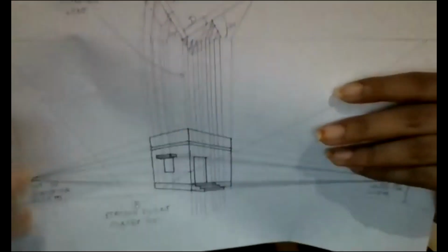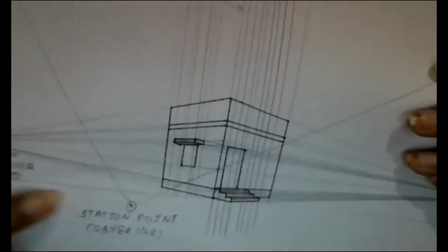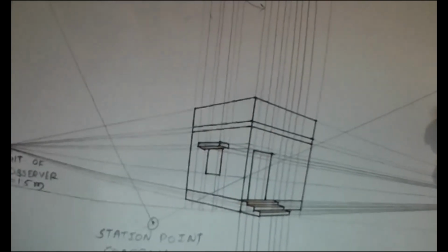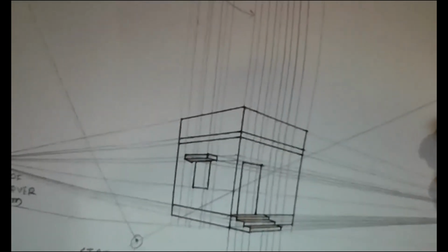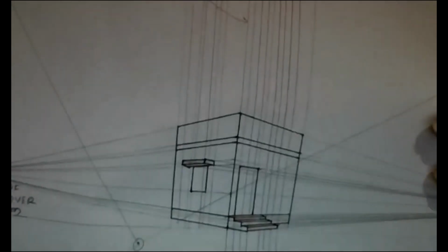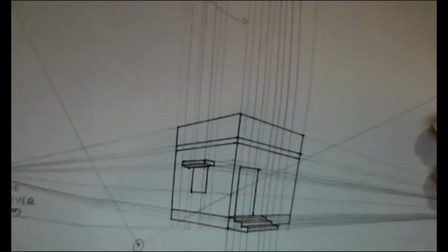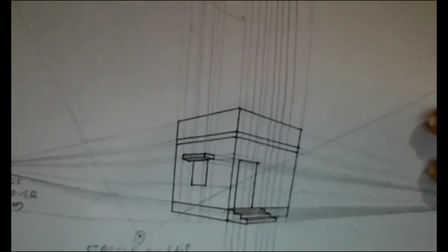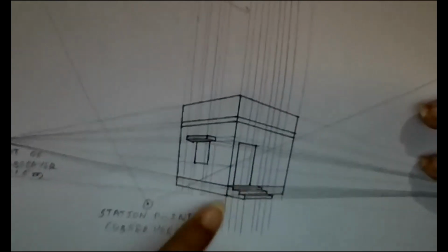I'm showing you again the perspective view which I have drawn on paper. You can see here are the entrance steps. 3 entrance steps are drawn. And you can see there are lots of projections, but you can clearly see the steps. Because I am using the scale 1 centimeter equals 1 meter, it is a little bit congested. If you use the scale 1 centimeter equals 0.5 meter, it will be more clear. Okay, so your final perspective view will look like this, which we have learned from part 1 and part 2 of this video.